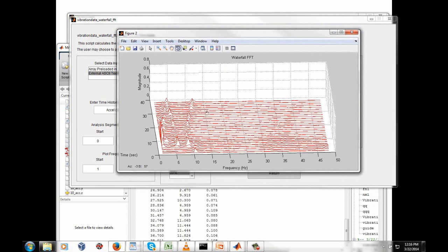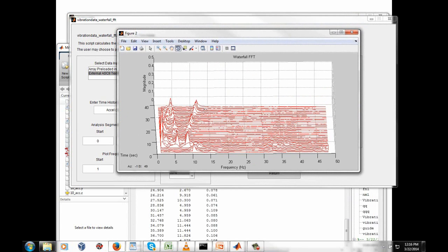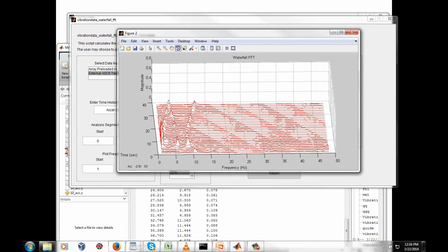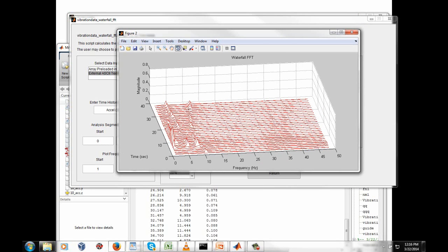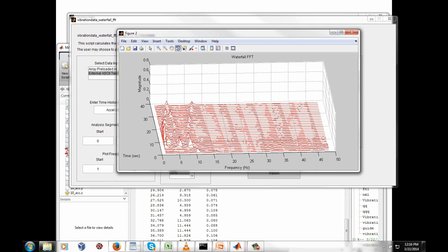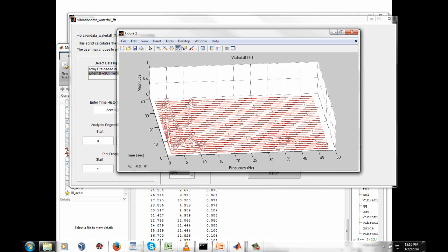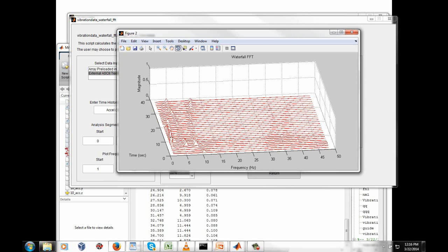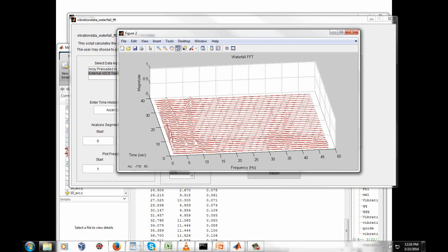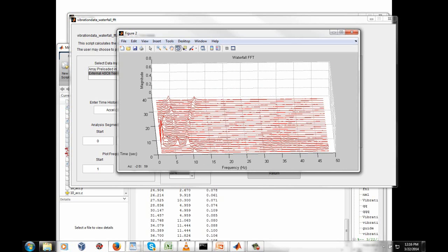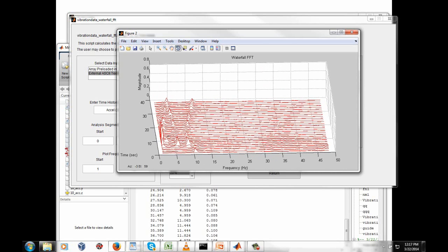We've gone down to lower frequency and changed the processing option. And we can kind of see these 5 Hertz peaks here. We can see the bending motion, the bending mode action as well. And down at low frequencies, we're actually picking up some kind of low frequency noise, maybe even some rigid body acceleration that makes it a little harder to pick out the 2.5 Hertz action.